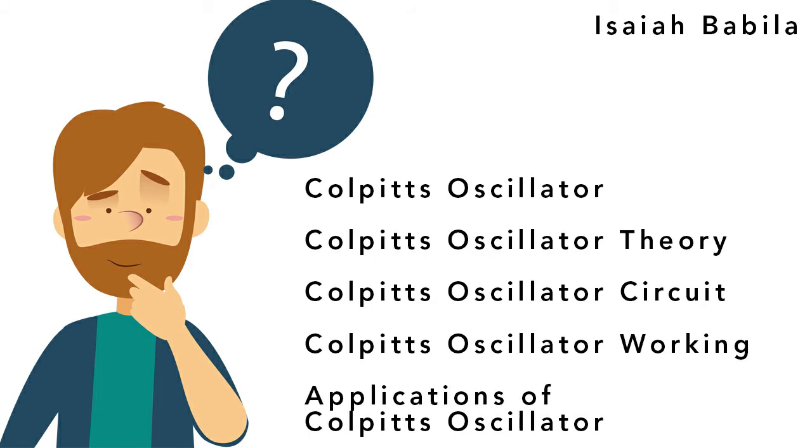Resistor 1 and resistor 2 form a voltage divider and provide bias to the transistor. The circuit consists of an RC coupled amplifier with a common emitter configuration transistor. The coupling capacitor Cout blocks DC by providing an AC path from the collector to the tank circuit.